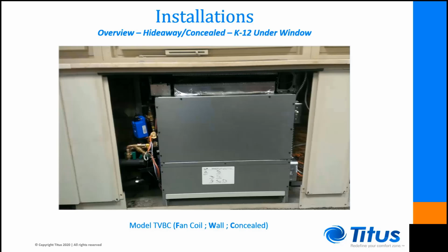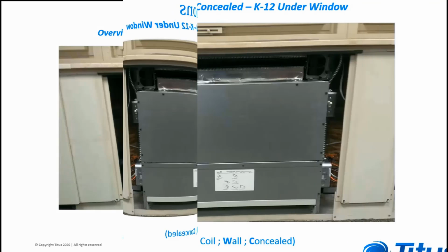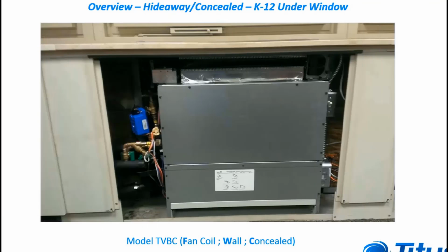You may recognize this unit as we discussed it earlier. This is the TVBC unit and is a floor-mounted unit meant to be hidden from view. In this project, instead of being hidden behind a wall, it is being installed into a pre-existing cabinet structure and will discharge air vertically into the living space. An access panel will be put in place in front of the unit to hide it from view. The access panel will have a louvered section to allow for return air to come into the unit for conditioning.